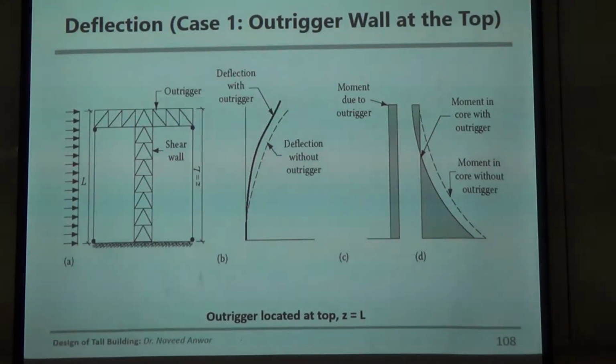That is a limitation. The shear still needs to be carried by the column shear and the core wall or the walls. So that does not help. There is always a limitation that if you have a problem with shear in the shear wall, you cannot solve it with outriggers. Some people misunderstand and think that they can reduce the shear force in the core by adding outriggers. It won't work. It doesn't affect it.